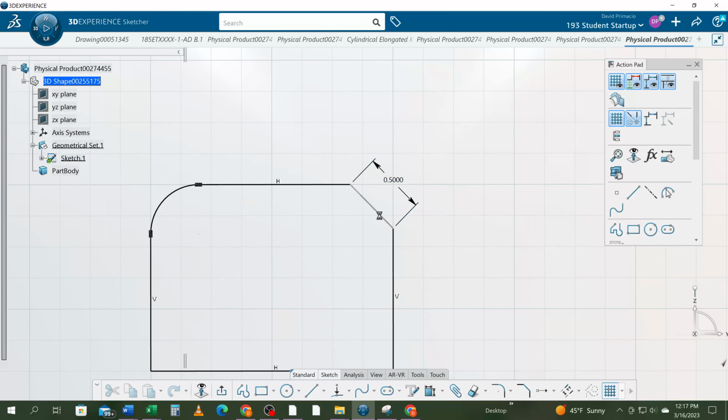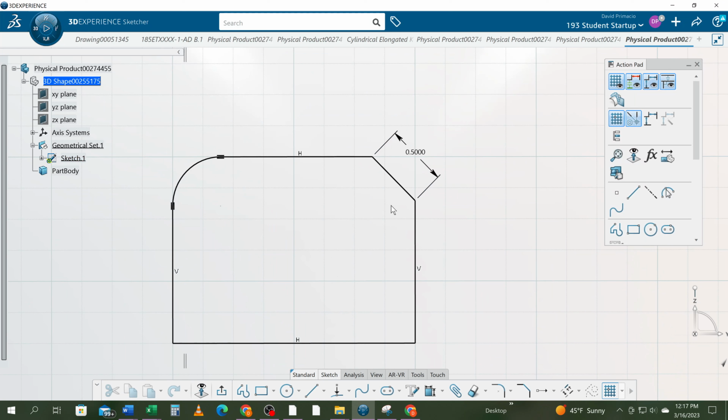But you don't want to tell the shop to make this line a 1/2 inch, because that's very difficult to figure out how to do, because their raw material looks like that. So how do you get it to be a 1/2 inch and equal distance on both sides? It's going to be really a big challenge for them. They're going to have to go get their geometry books back out and figure out how to do the math to figure out, if you have the hypotenuse at a 1/2 inch, what is your lengths of these lines using sine, cosine, and tangency? And who wants to do that anymore? And that's just not normally how that's done.